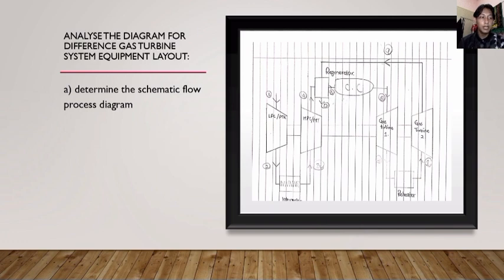in a boiler. The steam drives a steam turbine which also generates electricity. The exhaust gas is then passed through a regenerator to recover some of the heat and further increase the efficiency of the process. The use of intercooler, reheater, and regenerators in the combined cycle power plants allows for better heat recovery, increased efficiency, and improved power output.